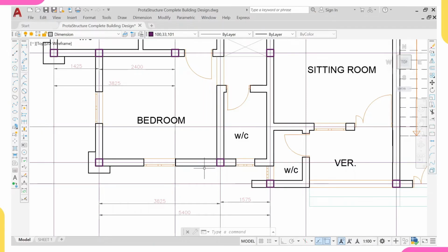Maybe your client might have done works or projects where all through it is 2Y16. You should be able to explain as an engineer. Maybe in the project that he carried out, he has a column here and also here, because if you have a column at this point, there will be high probability that you'll be having 2Y16. But if I'm having 5.4, there is high probability that I'll be having 3Y16 here. So explain to that client that you are trying to save cost. That's why you remove this column and then replace it with 3Y16 instead of 2Y16.